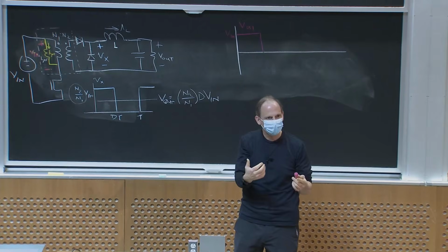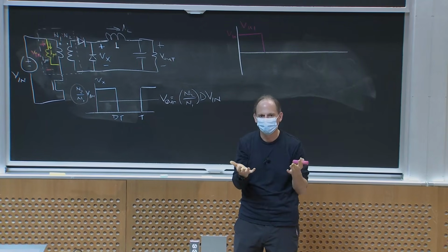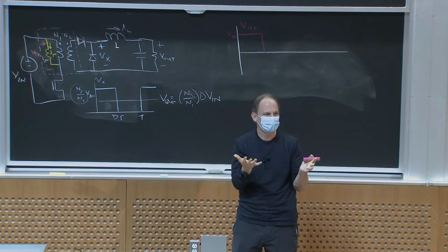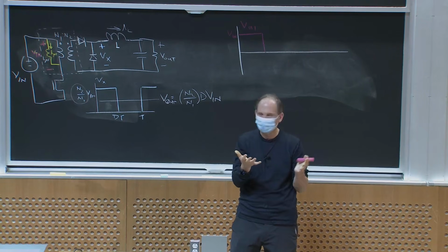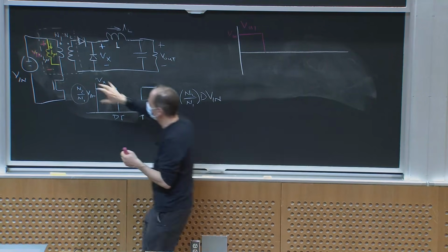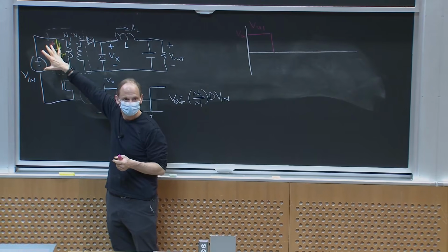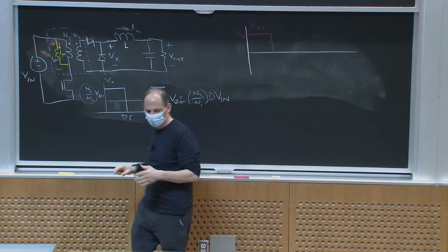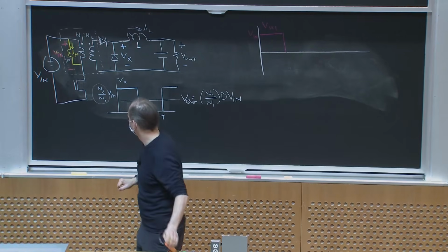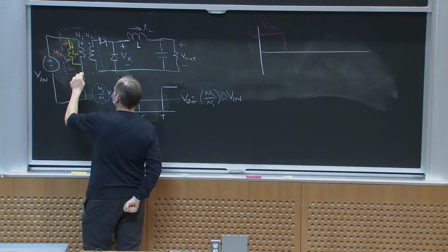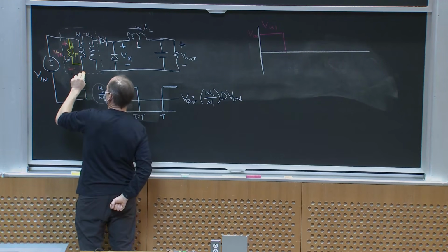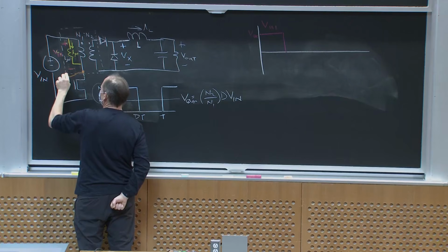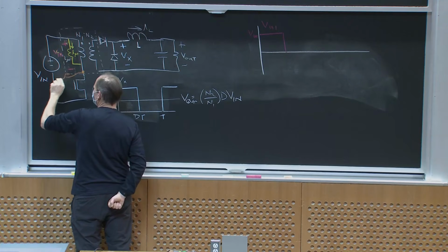Okay? So what can I do? I got to provide some other place for that magnetizing current to flow. And in the process, I need to apply a reverse voltage on V mu 1. Okay? Now, there's a lot of ways I could do that. One very popular way is to provide a voltage here and maybe put, say, the equivalent of a Zener diode here.